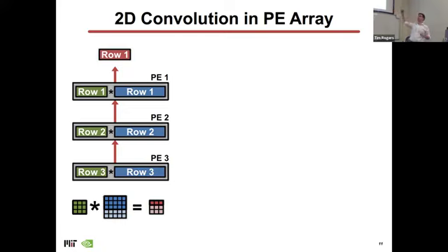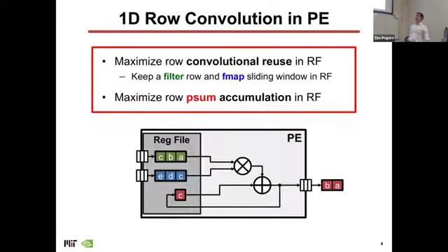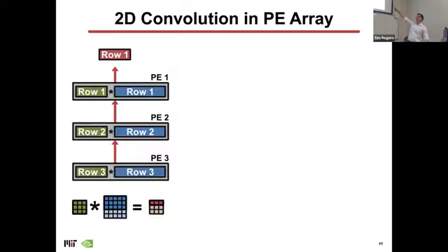And the way you do this is with that output. In that previous slide, I was sending the output out in this little FIFO buffer. I'm going to send the output out to another element that's responsible for another row, and it's going to take that incoming partial product and add it to the product that it's creating. And then, as you might guess, I need another row.